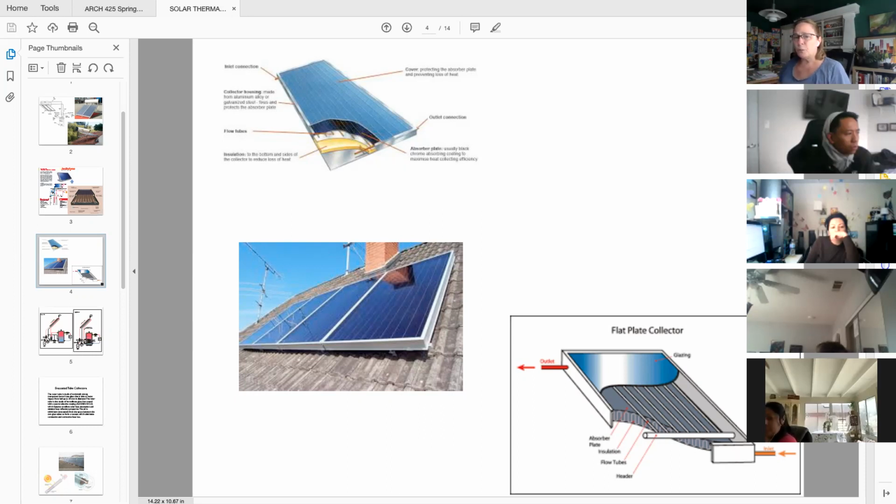Because solar thermal panels are heavier, you need to have them well mounted and that load taken into consideration for your roof framing. PV panels are really lightweight. Their mounting is a lot easier because they're just lighter weight. They don't have the copper in them.